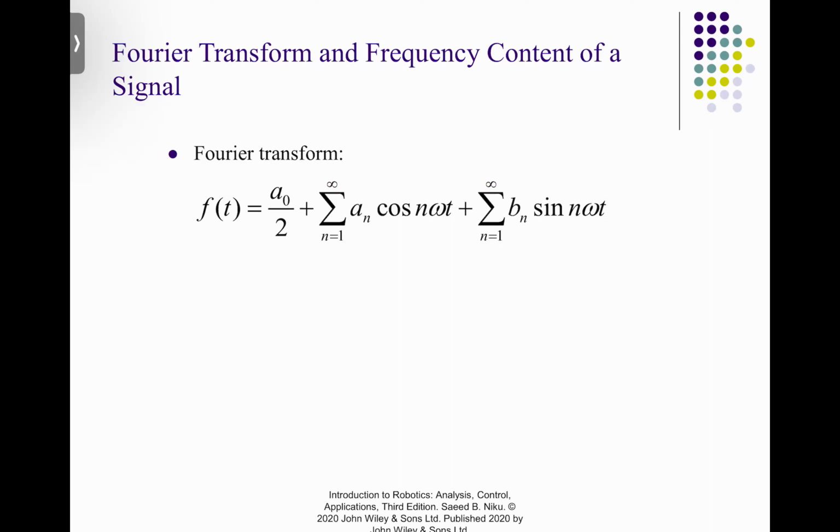Remember this. Fourier series means that you have a periodic signal that spans the entire time axis. Now, what it means is if I have a signal which is something like this, I cannot apply Fourier series to this because this signal is not repeating. But if you perform the Fourier analysis on this non-repeating signal, that is the Fourier transform.